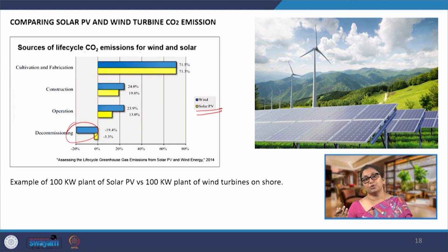Not encouraging transportation of a type of energy source to far off sites. However, in certain cases, for example in hills, solar PV is equally unavailable as wind would be, but it is easier to transport and also easier to install and function because there is probably good sunlight available. So, that feasibility also will have to be checked when we are talking about overall feasibility, not only from the scope 1, 2 and 3 emission point of view.